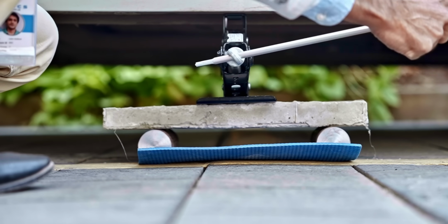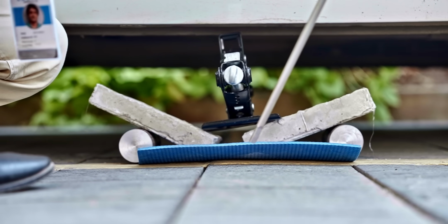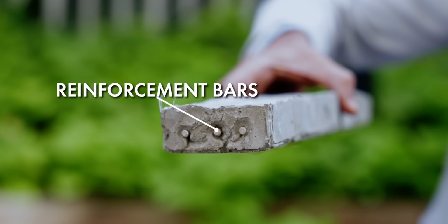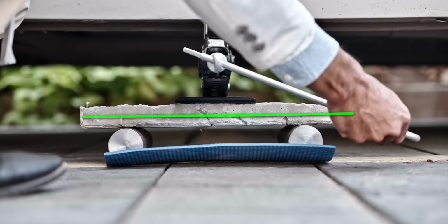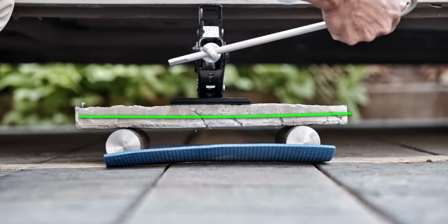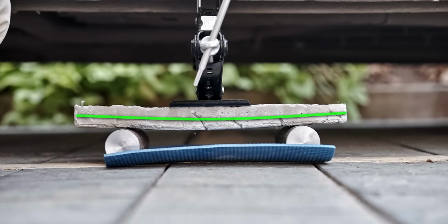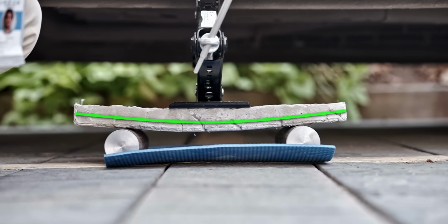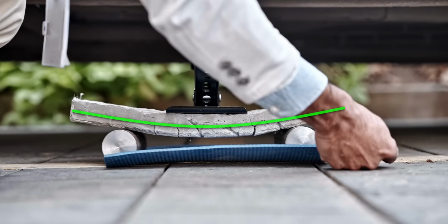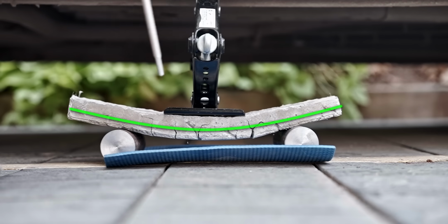This concrete block has no reinforcement and breaks suddenly without carrying much of the car's weight. In the second block, I have added a few reinforcement bars towards the bottom. Now you can see the concrete is developing small cracks at the bottom. The car is almost fully up. The block has transformed into a beautiful curve with a lot of cracks. Yet the block is able to carry the car's weight.